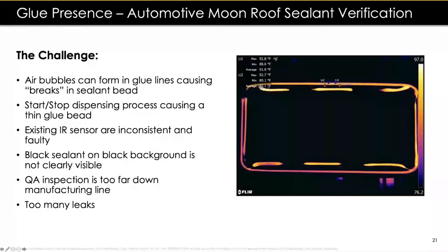So again, with thermal imaging, we map around here, saying this is where the adhesive should be present. This is the start and stop, and we want to validate that. A pretty simple process, and it was highly successful.